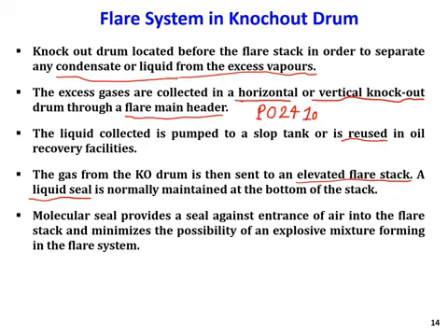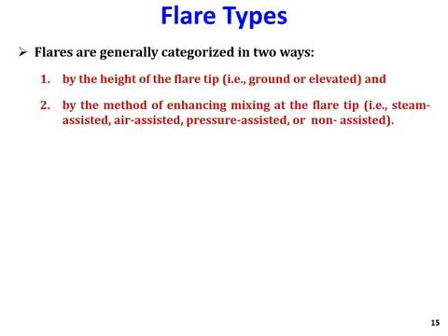So molecular sieve, what it does, it provides a seal against the entrance of the air, so it doesn't let the air go through the flare, and it minimizes the possibility of some issues like explosion of the mixture inside the flare system. So that's also another importance of molecular sieve that we have.